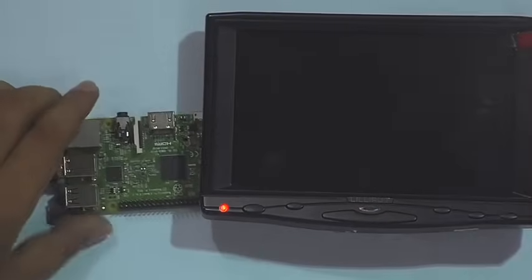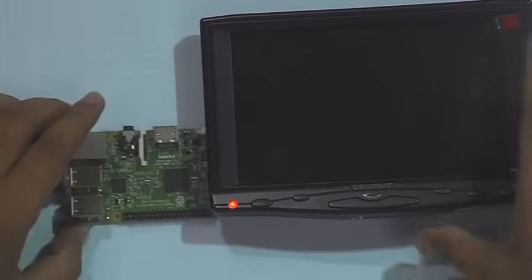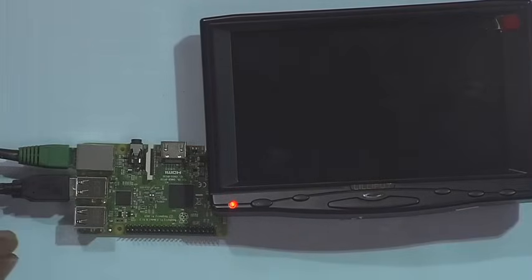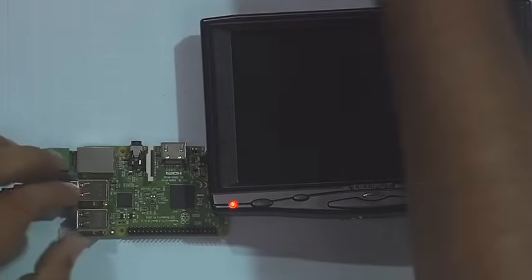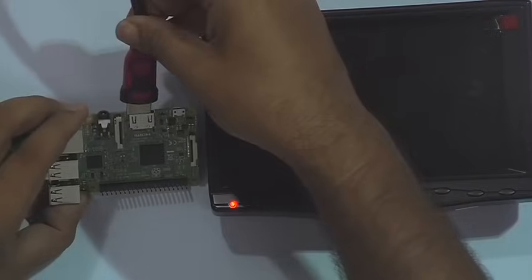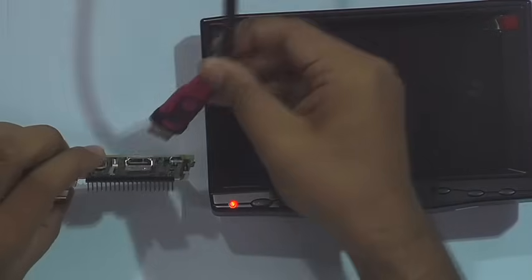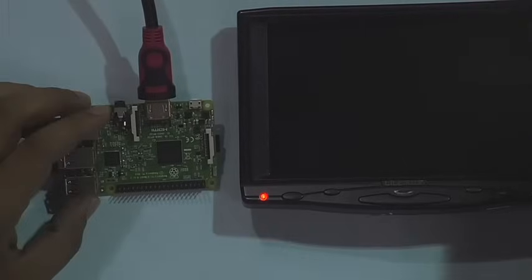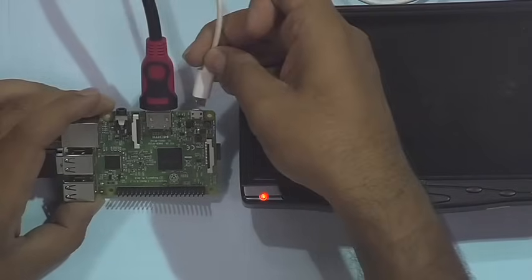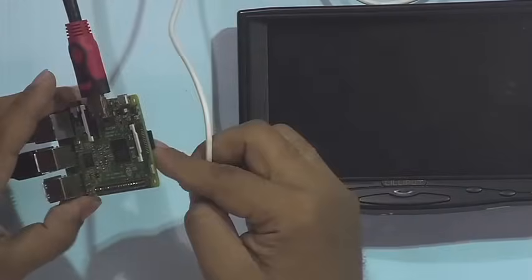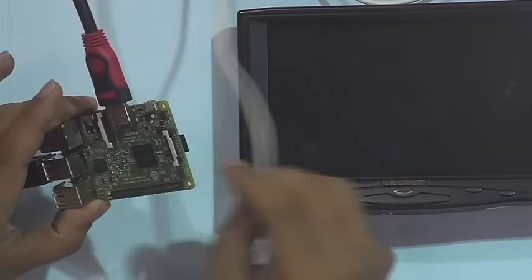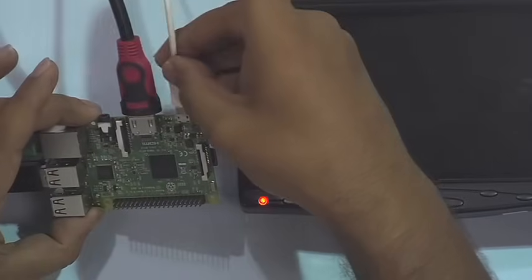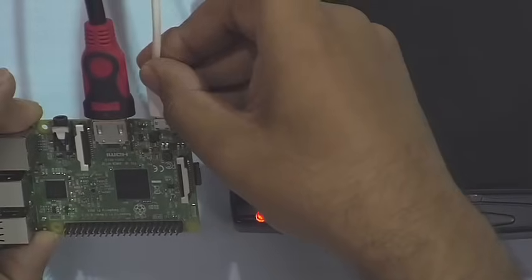This is a small monitor, portable monitor. So it is being powered by an external power supply, and it is connected. It will be connected to the Raspberry Pi via this HDMI cable on this HDMI port. So once all of these have been done, you just plug in your power supply for the Raspberry Pi. You already check whether you already have the memory card in place. So it is there, you just plug it in.